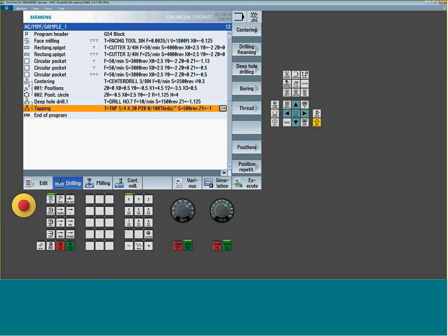And now I want to call up the 4 outside positions. So again, I could copy and paste that down here, but now I'm managing the same locations in 2 different spots. Or I can use the position repeat field. I just want to pay attention to the number that was associated when these positions were built. It did that automatically for me.